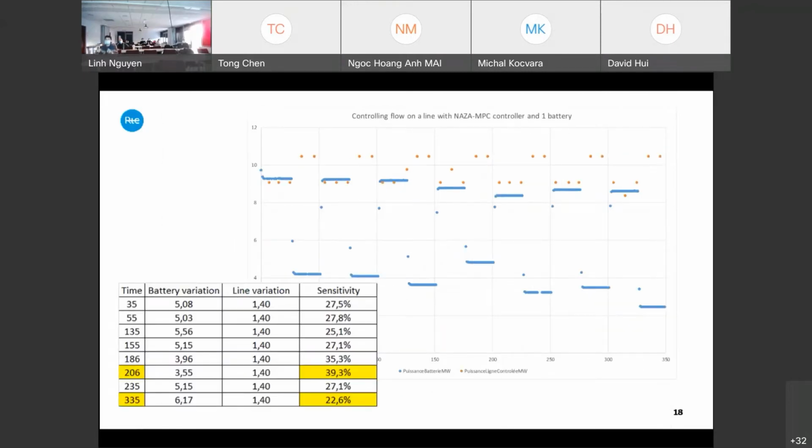One question: the optimal control problem you consider, is this actually a time delay optimal control problem? Are you modeling it like this? Yes, we have time delays. We are really embedding in the MPC optimization problem the fact that if you decide now to curtail, the curtailment will be effective in 45 seconds. Okay, so this is in the MPC. Yeah.